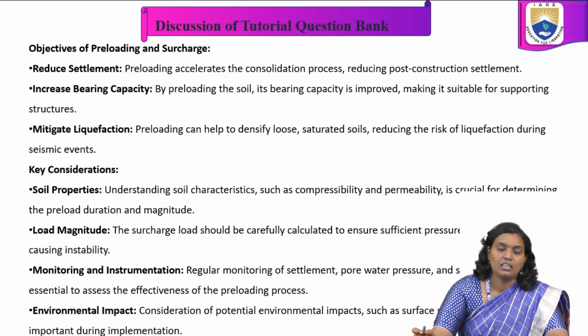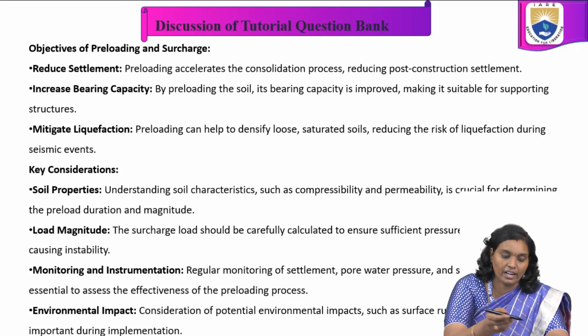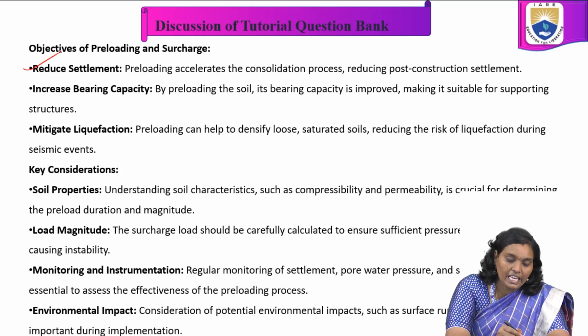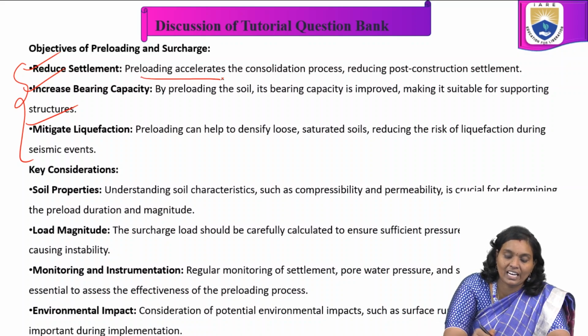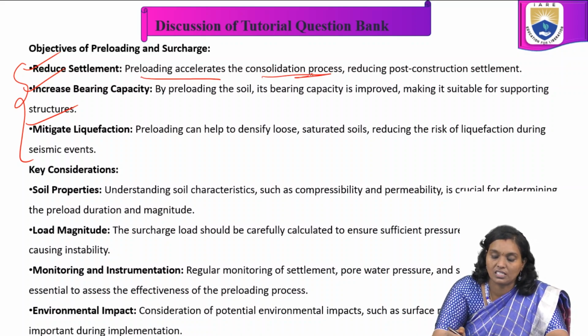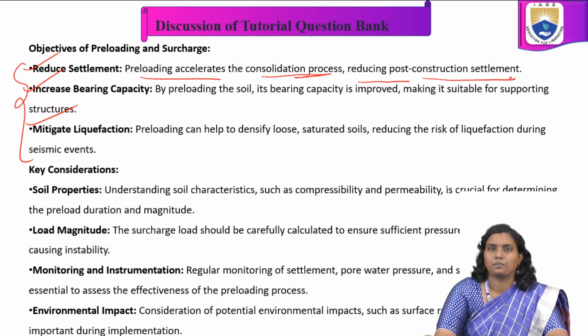In this, different objectives are involved. Those are reduce settlement, increase bearing capacity, and mitigate liquefaction, the main objectives of preloading and surcharge. Reduce settlement: preloading accelerates the consolidation process, reducing the post-construction settlement.